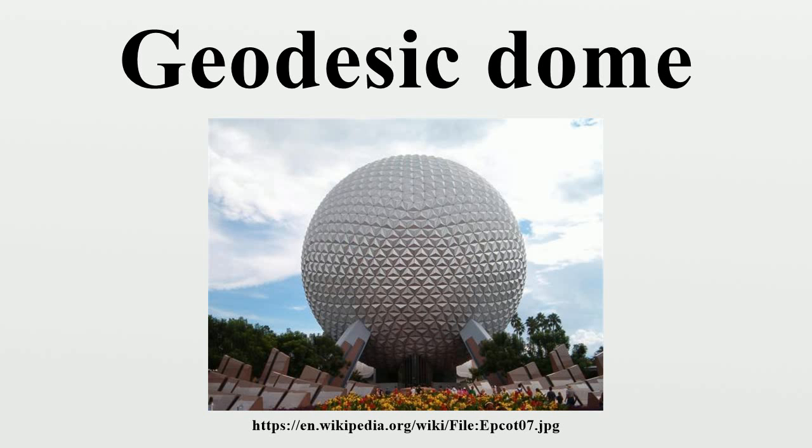Methods of construction. Wooden domes have a hole drilled in the width of a strut. A stainless steel band locks the strut's hole to a steel pipe. With this method, the struts may be cut to the exact length needed. Triangles of exterior plywood are then nailed to the struts. The dome is wrapped from the bottom to the top with several stapled layers of tar paper, in order to shed water, and finished with shingles.